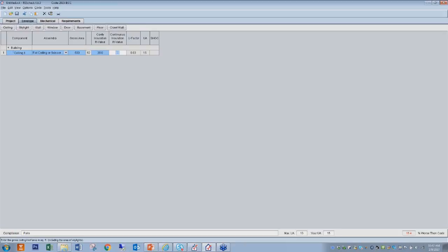Questions come in, and I've seen several reports this way, is, no, I have so much insulation above my trusses. That's continuous insulation. Yeah, it is, but the software already runs that calculation. If you are blowing in R38, if you're laying in R38, one application is cavity. The R value is what determines the amount of inches above those trusses that the software will run another calculation in the back end for that overall U factor.